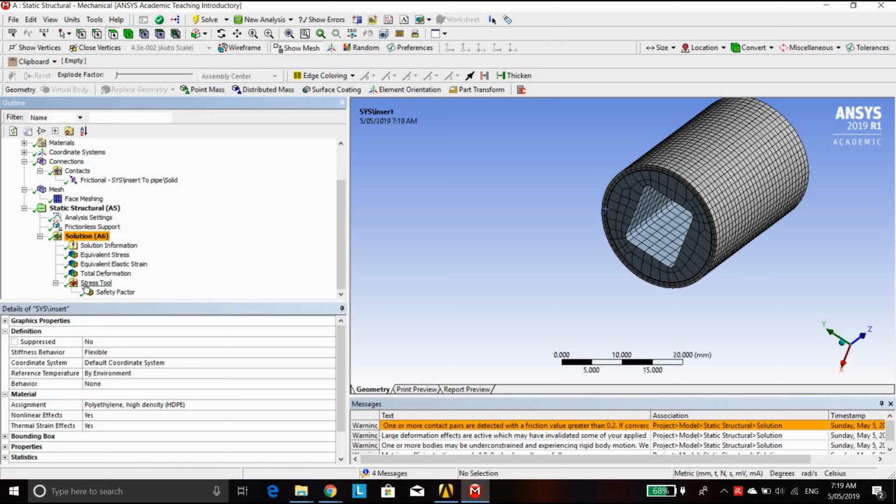By the way, if our material had an SN diagram, you could check the fatigue calculation for them. So if you were interested, add an SN diagram to your material and investigate how many times you can push pressure fit that elastomer inside that pipe. It can be interesting.